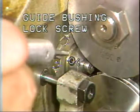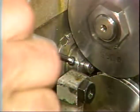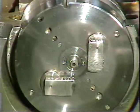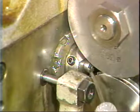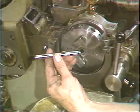Located here is the lock screw that holds the stock guide bushing in place. To remove the bushing, loosen the lock screw. Next, make sure the tool holders are moved out of position on the front of the tool head. Push the bushing forward and pull the bushing out the front of the tool head.